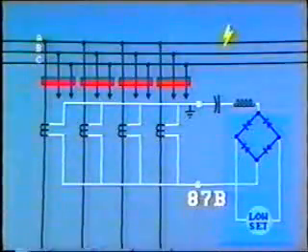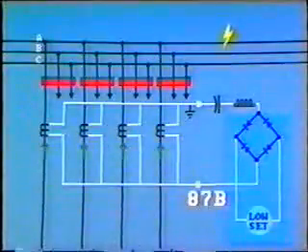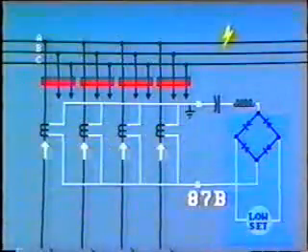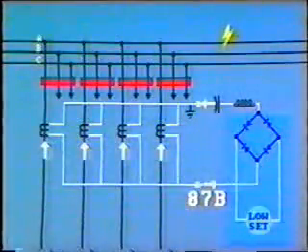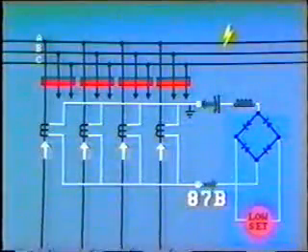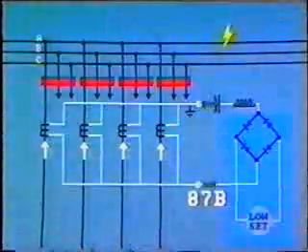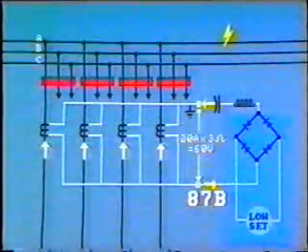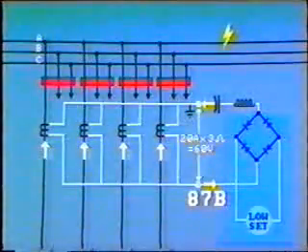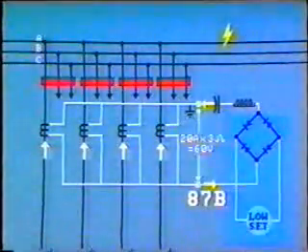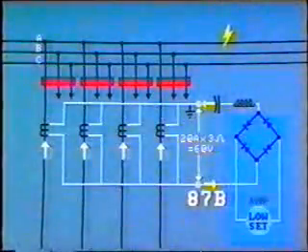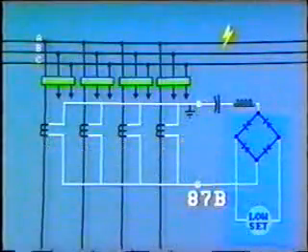When there is an internal fault on the bus, all of the circuits will feed into the bus, and therefore all of the secondary currents will be additive. In this situation, all of this current must flow through the differential relay and operate the tripping circuit. An out-of-balance current of, say, 20 amps flowing through the CT circuit of, say, 3 ohms would produce a voltage of 60 volts across the impedance relay.